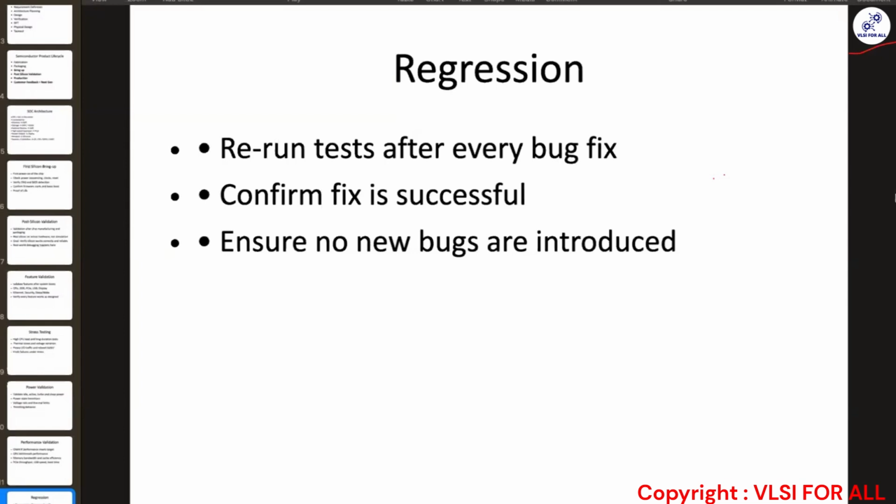In the triage part, you may have to figure out, if it is your display, you connect one particular display and you are seeing this enumeration problem. You may have to test with a different monitor as well to make sure that it happens with all the monitors or only with that specific monitor. So you check all the possible triage scenarios after filing a bug, and then you put all of those details in as well. And then eventually it goes to the debug.